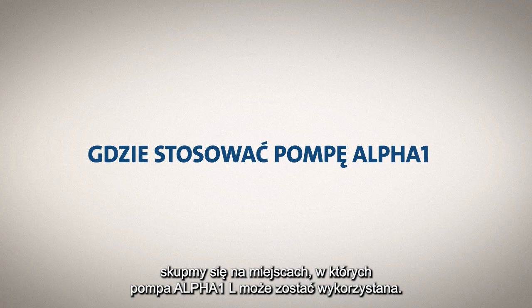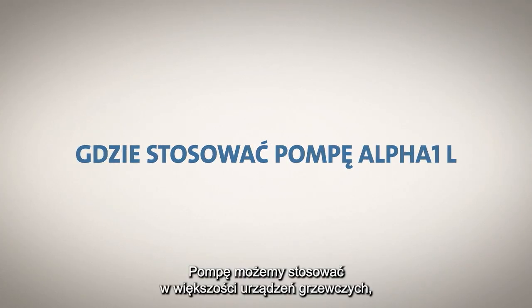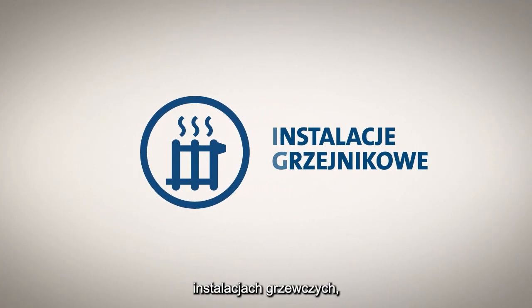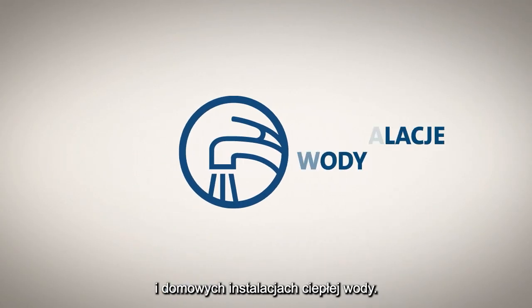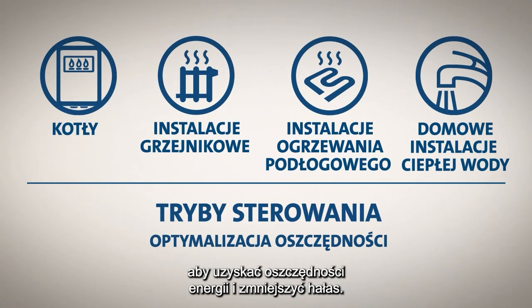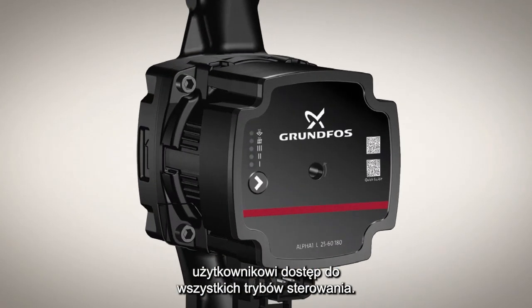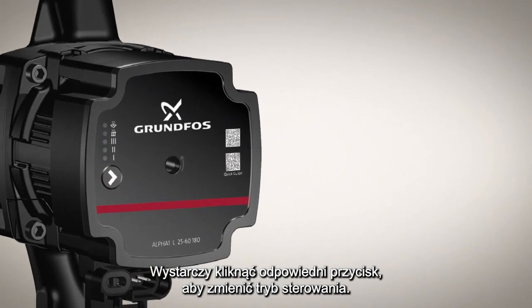For a start, let's look at where an Alpha 1L can be used. The pump can be applied in most heating applications including boilers, radiator systems, underfloor heating systems, and domestic hot water applications. For each application, specific control modes have been developed to optimize energy savings and reduce noise. All control modes can be accessed by means of the intuitive user interface. Simply click the button to toggle through the different control modes.